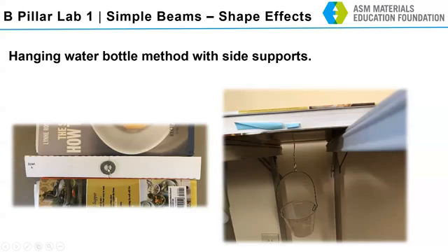So we stuck an opened up paper clip through our beam, and then to spread that load out and keep the paper clip from pulling out, we put a washer under it. Okay, it's just to keep that wire from pulling out. And here's my cup hanging underneath. So I'm just going to add water or hex nuts or any other source of mass to that.